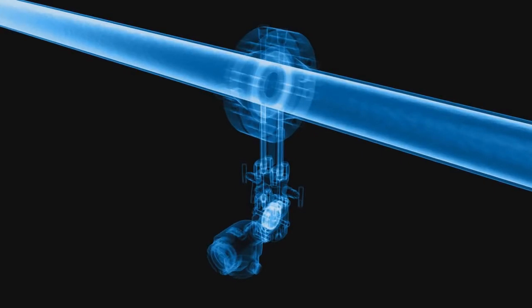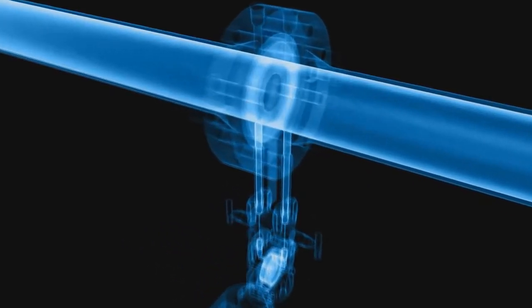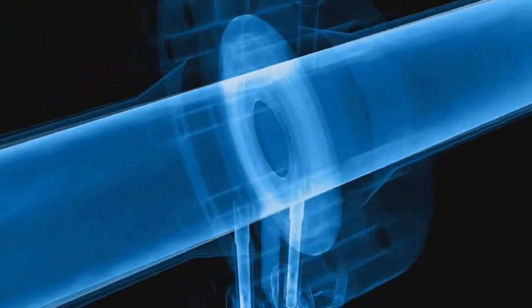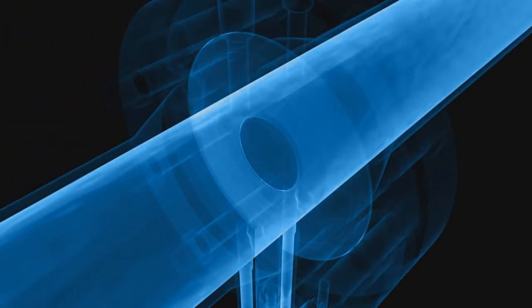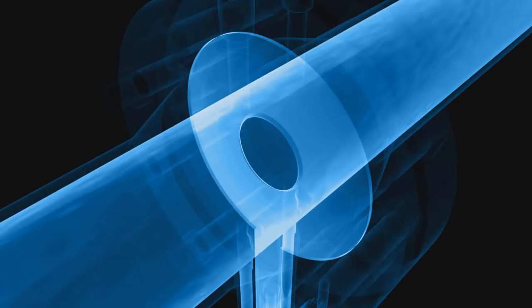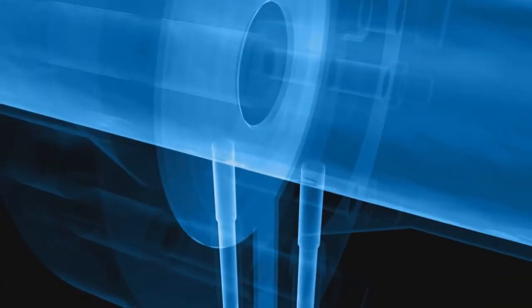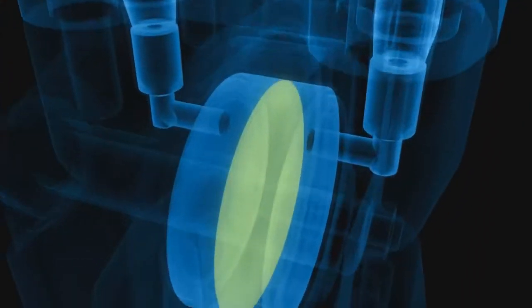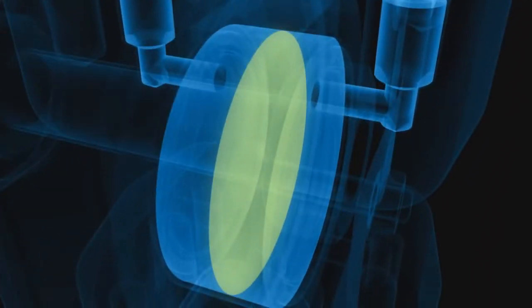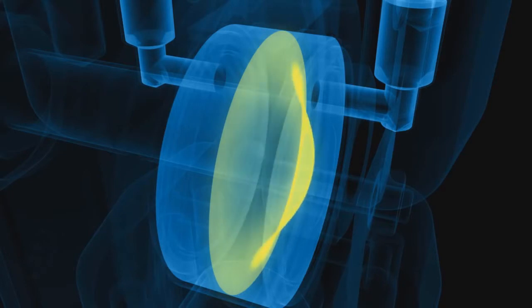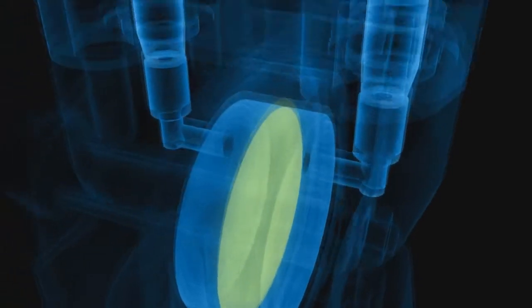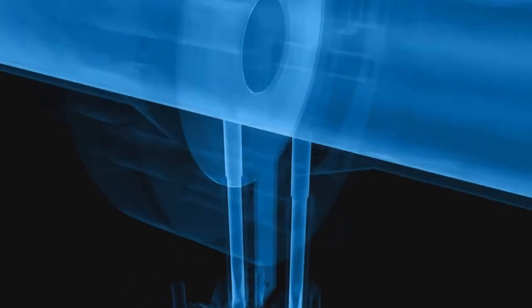Differential pressure flow meters have an artificial restriction integrated into the measuring tube, illustrated here by the example of an orifice plate. Two holes are located in the pipe wall, one before and one after the orifice plate. Two separate tubes connect these holes to a differential pressure sensor with its two pressure chambers separated by a diaphragm. The tiniest pressure differences in the flowing fluid can be precisely measured.